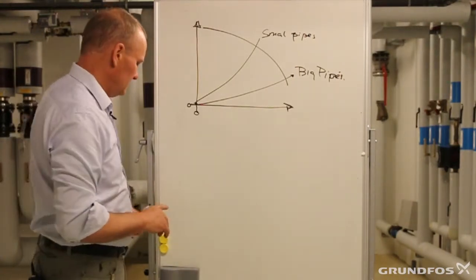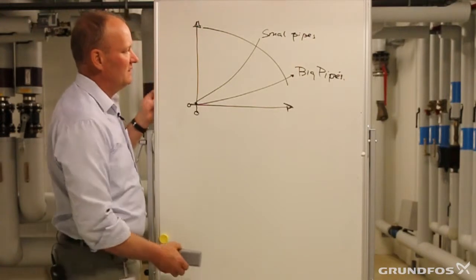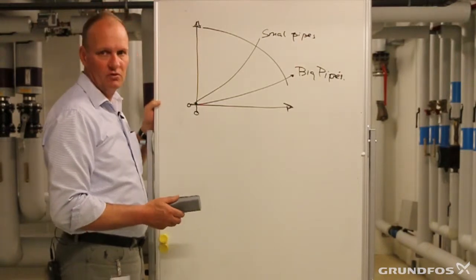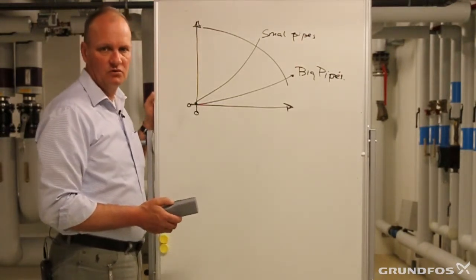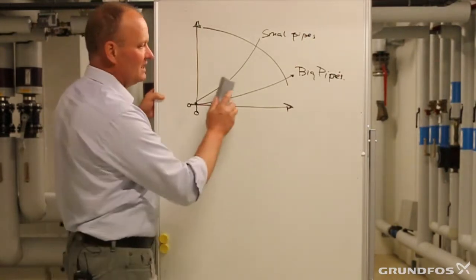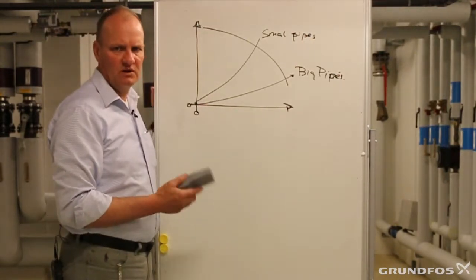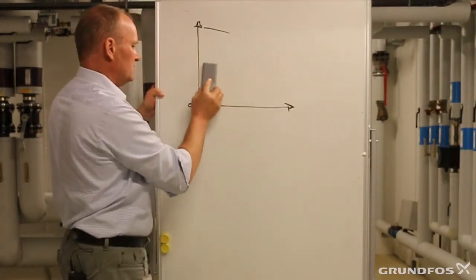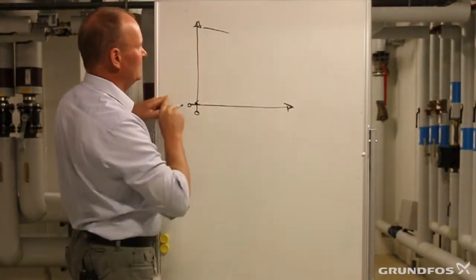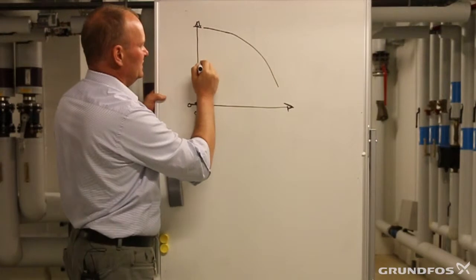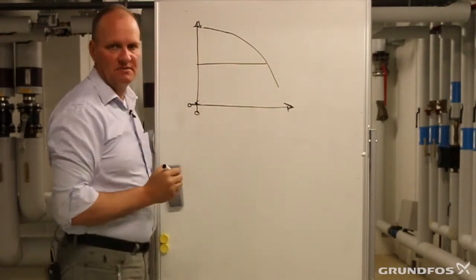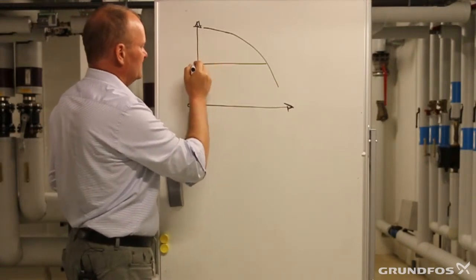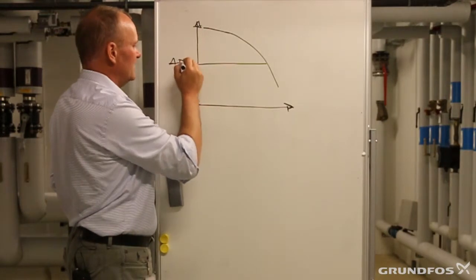But when we know that, then that's also the reason why we have different control possibilities, the different control modes for all of our e-pumps. So let's just recap about what kind of control modes we actually have. So let's just redo this one partly. And maybe as you remember we discussed, we had something which we call constant pressure, constant differential pressure actually.